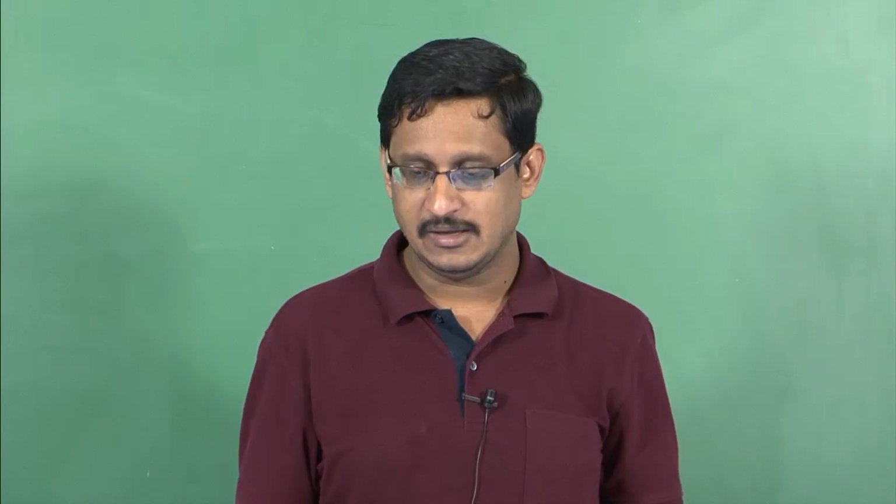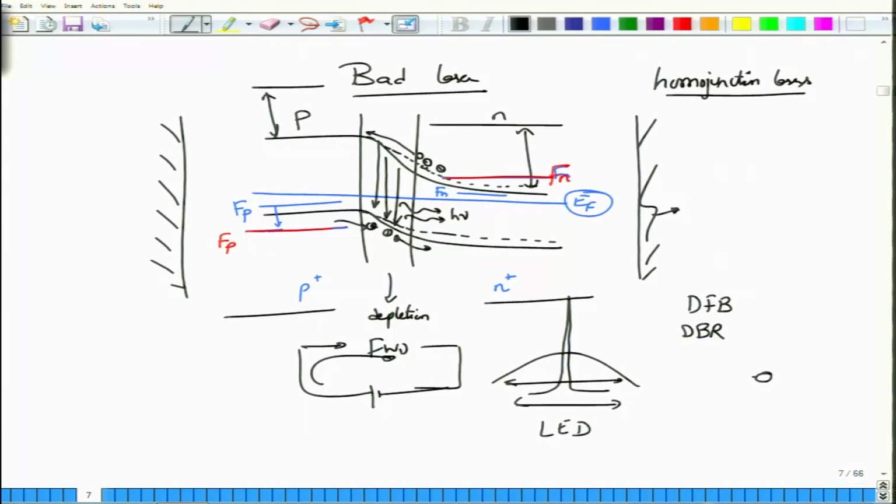Unfortunately, it is bad, because of the length over which an electron can move and the holes will move into the layer, thereby causing the inversion layer. So, this is the depletion layer for the electrical case, but this is the inversion layer for the laser application, because there is an abundance of electrons and an abundance of holes which can then recombine in these regions. So, they are pushed and they recombine.